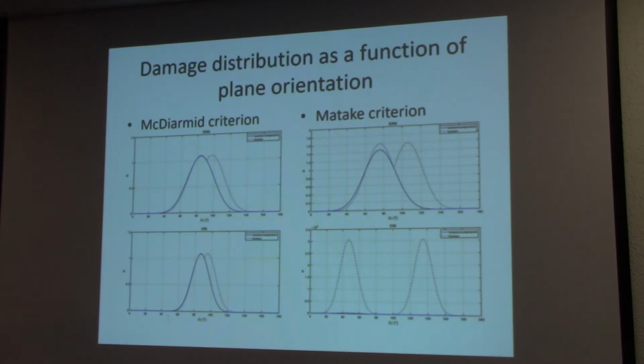But if you have the loading sequence which is composed of multiple loading cycles, and each of them has a different orientation of the principal axis, you will have to use a different approach. You will have to assume all the damage in each plane, and then you are now assuming the damage from a non-critical plane, which is actually higher than the critical plane damage. So it means that your criterion gives you very conservative results.